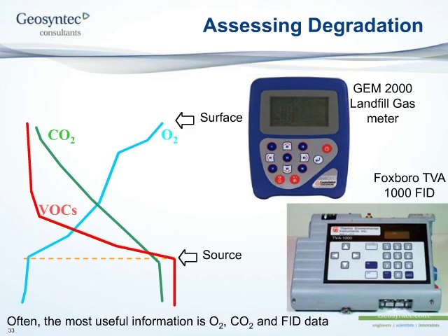So a photoionization detector won't detect methane, but a flame ionization detector will. So a slightly different set of kit is usually required for assessing petroleum hydrocarbons. Next slide.